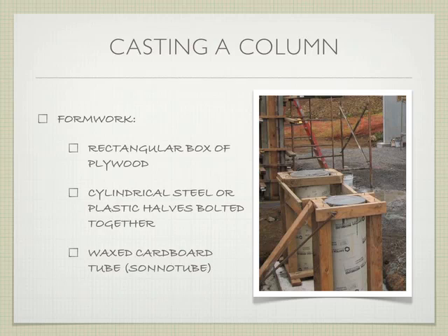The last option is basically like a toilet paper tube that has wax on the inside. It's called a Sonotube. That's the brand name for it. But basically it looks something like this. It's a giant paper towel tube or toilet paper tube, wax on the inside. You slide that over your column, and it provides basically the formwork for it. Pretty convenient because you can unpeel it and expose the concrete after the fact, though a lot of times people just leave it, and it eventually degrades with water and what have you. Very common, very inexpensive, which is a good thing.